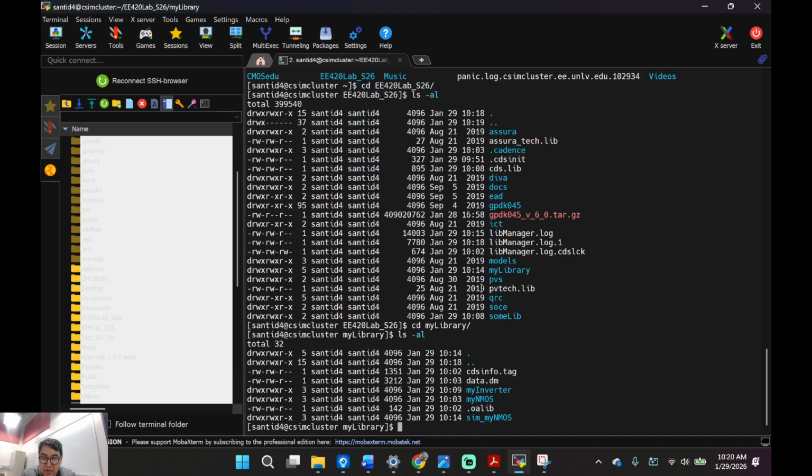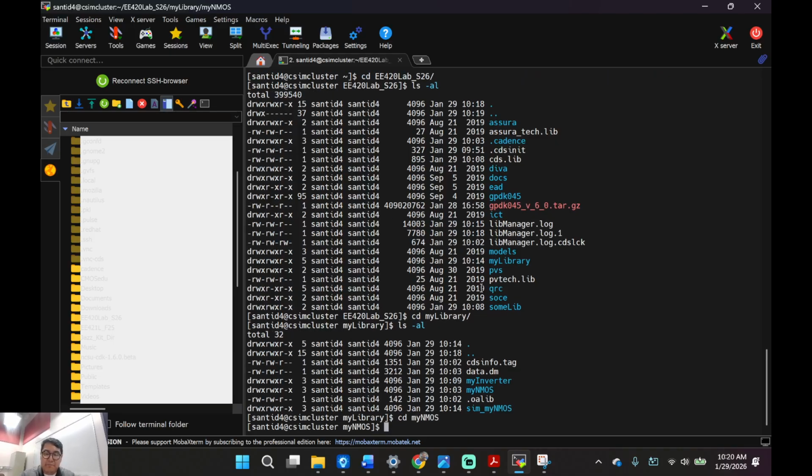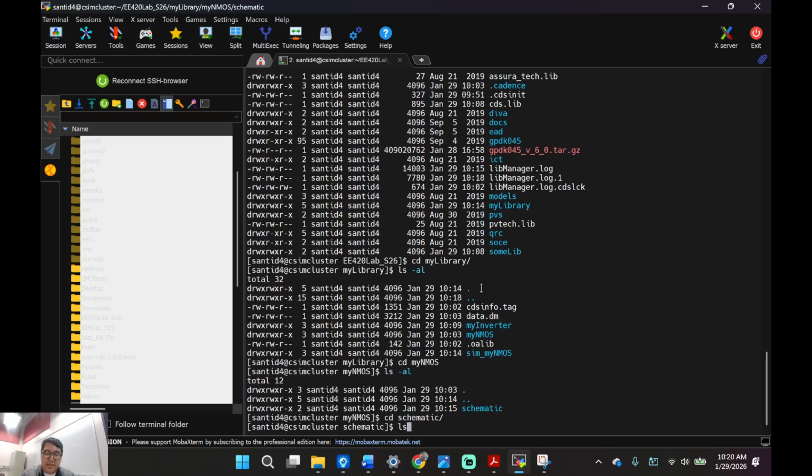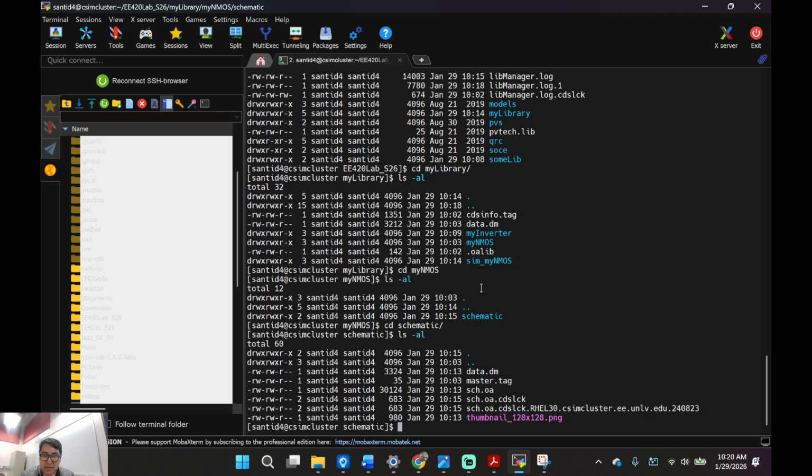Go into cd my NMOS, ls -al. Go into cd schematic, ls -al. There it is.